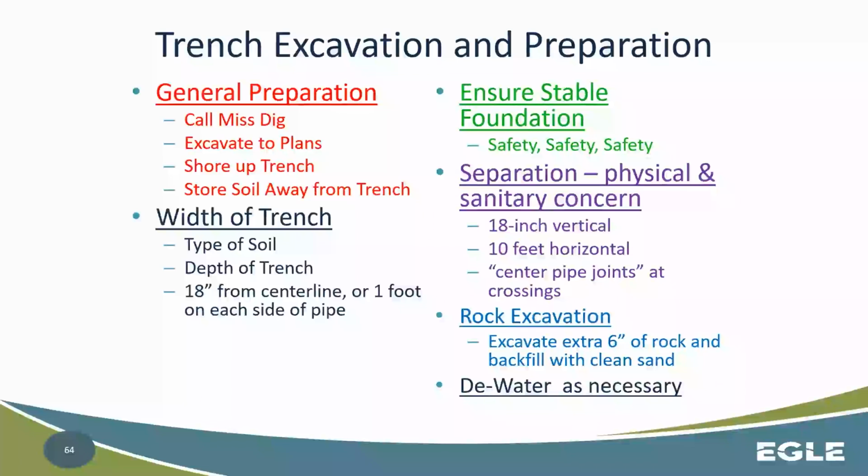Okay, so general preparation, call Miss Dig. Make sure you're not tearing up a gas line, electrical line, whatever, expenses and safety concerns there. Excavate to the plans. Make sure you're meeting the plans the way they're drawn up. Shore up the trenches. Make sure you're not having those cave-ins. Store soil away from the trench. Again, kind of driving that point home. Making sure that you have true trench safety, especially if somebody's getting down in that hole.